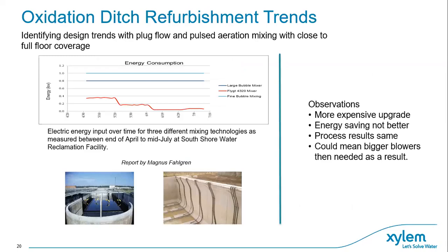One other thing that we want to highlight is there are some trends on mixing with air on the market, and it's claimed to be efficient. It works, but in our view, it's not efficient. If you think about having a room full of balloons and letting them go, and that's supposed to create mixing, you need a lot of balloons, and compressed air actually costs more to produce than if you have mechanical mixers creating the mixing effect. So this curve is actually showing what the difference is.